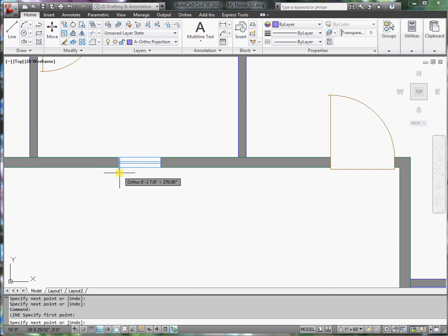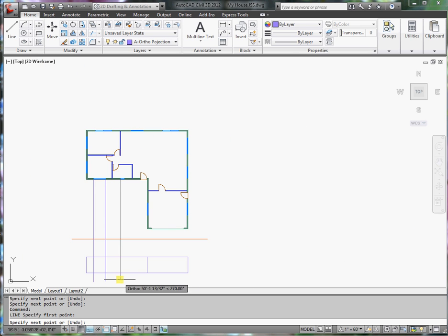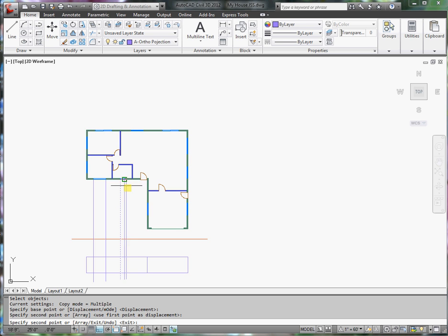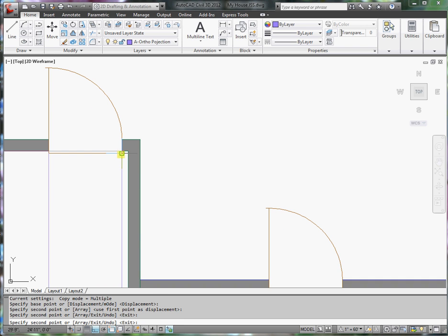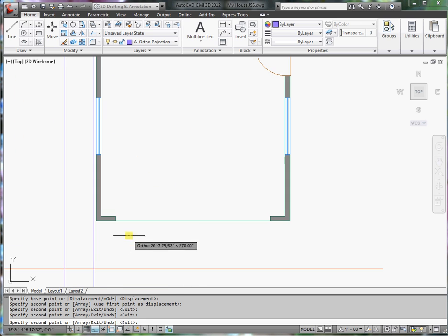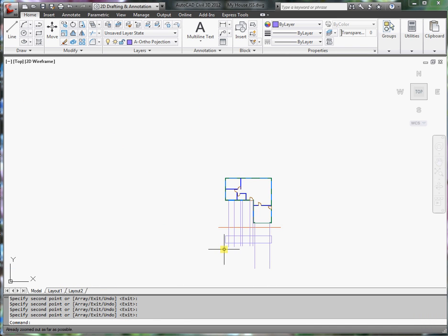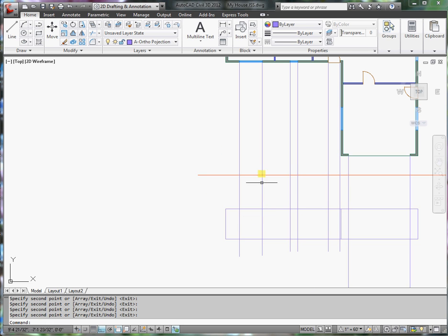Have another window. Now I'm drawing these. The other option that I have is I can copy that line, reference the endpoint here, and just snap to endpoints. Better zoom in to get that endpoint right. And I'll have the garage door as well. All right. These are the projection lines to locate where the windows are on this particular elevation view.